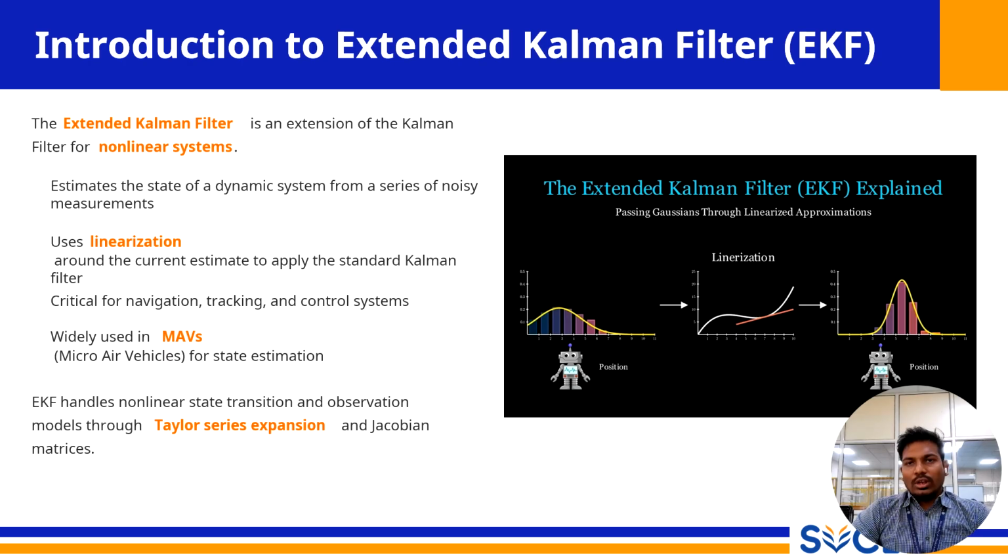The original Kalman filter is a landmark achievement in estimation theory, but it has one major limitation. It only works for systems whose dynamics and measurements are described by linear equations. Unfortunately, the physics governing aircraft flight are highly nonlinear. The EKF is an ingenious adaptation that allows us to apply the power of the Kalman filter to these real-world nonlinear problems.